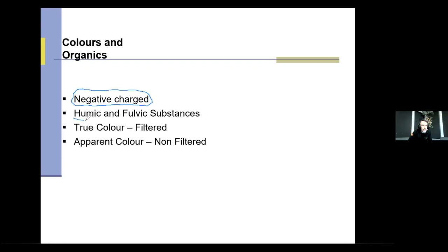What's in there is sometimes you get these humic and fulvic acids, right? If we've all had a cup of tea, we've basically put leaves into water, and these leaves will impart a color into the water and a taste. And that's really what's happening in nature as well. What you're getting here is these humic and fulvic acids are substances that are washing into the water. For us, when we make tea, that's a pretty tasty thing. But when it comes to putting this in our water, that sometimes can be a problem because our customer doesn't want water that looks like tea.